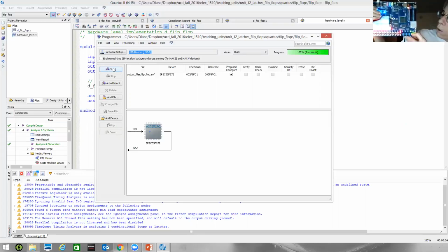All right, so when this is pressed, it's off. When it's not pressed, the green LEDs are on. I'm going to set my switch to 0. Then I said reset with key 1. So if I press key 1 and I go, notice that the output Q shown on red LED 1 is a 0. Right? If I hit key 2 preset, I let go, then we've preset that output to a 1.